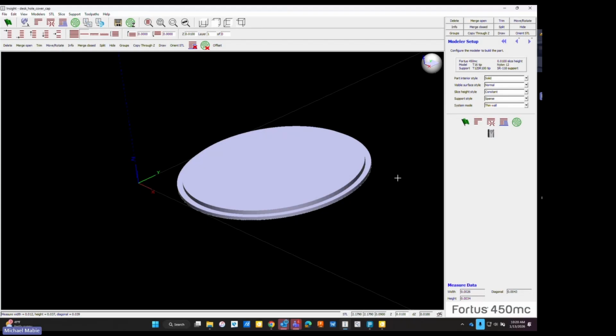But we can deep dive in another session on how we can build parts in the wrong shrink factor or the wrong system mode, and then use wall stabilizers and anchor pins to counteract the sinking or warping cases that might happen. Let's see, we kind of covered all that I was planning on for right now. It looks like I have a question here.